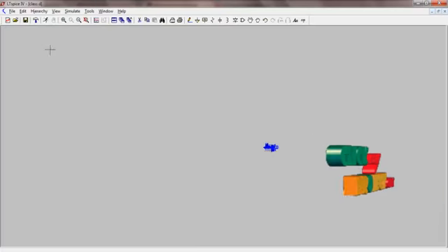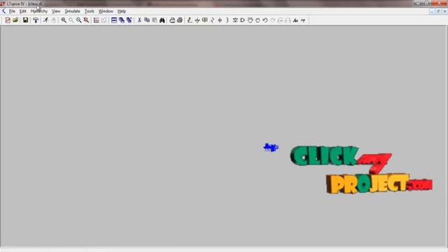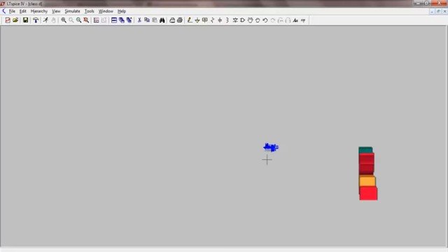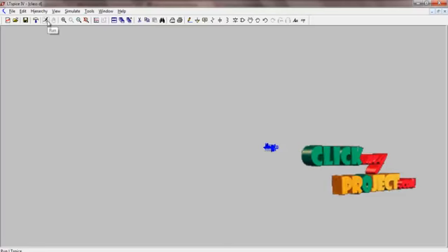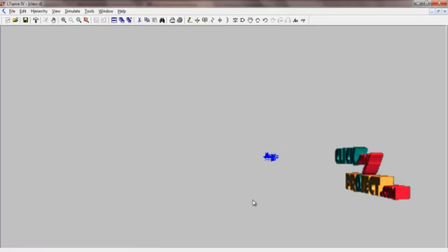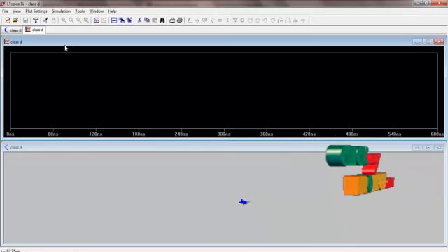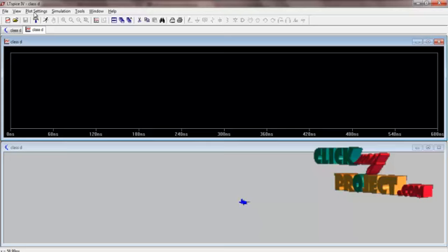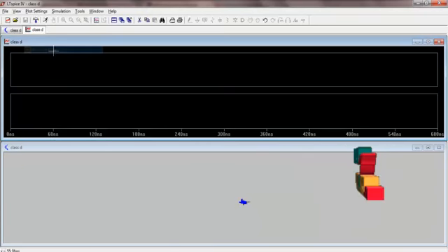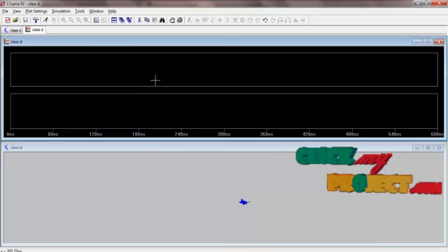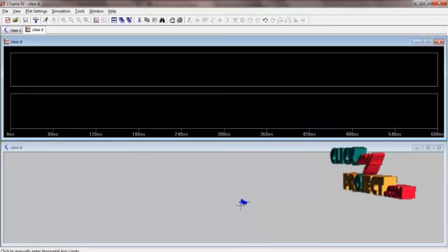Close this design. Our product is saved with the name Class D power amplifier. This is our design. In order to run this design, use the save and run option, and click run to run this product. This is an output waveform plot of our product. In order to add any plot, use the plot settings option to add a plot pane in this waveform window.